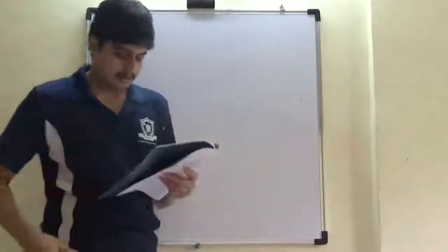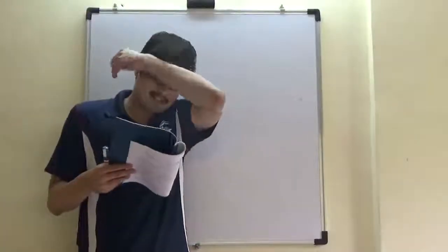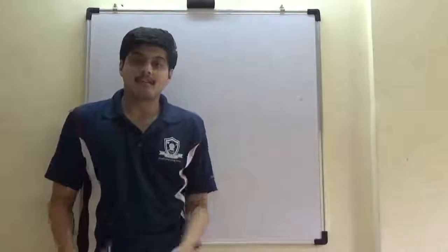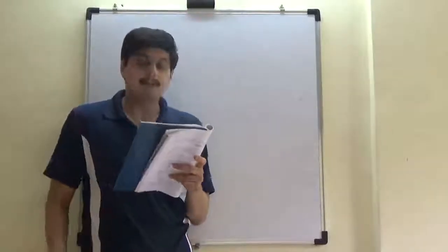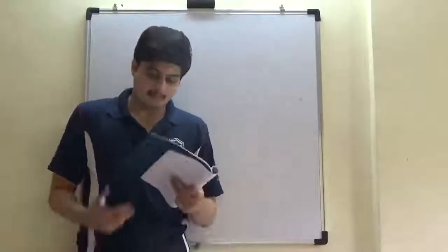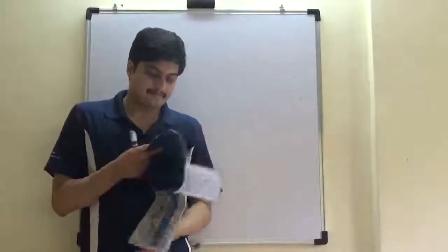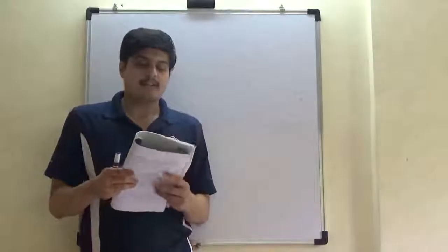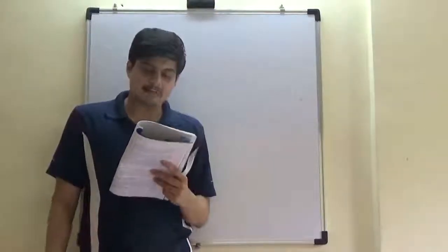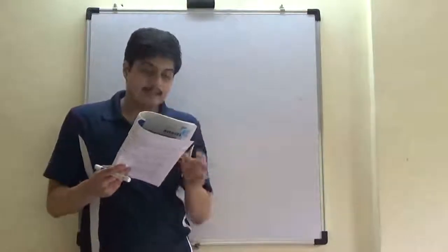Now there is one more thing called argument of periapsis. Now periapsis is the nearest point, right? When it is Earth, perigee. When it is Sun, it is called perihelion. Helios is Sun, right? When it is Moon, perilune. When it is Jupiter, perijove, right? So that is how you use. Then you have time of periapsis, which means the time of periapsis passage is the time in which the satellite moves through its point of periapsis.